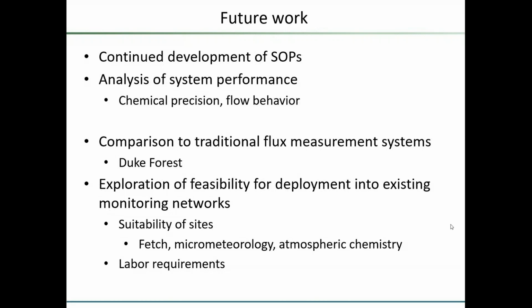Yeah, that's a good point, Brett. I think if you do sample too frequently at these low flow rates, you would run into that problem. The way that we do it is that at the end of every 30-minute period, we calculate the micromet parameters, and then based on what they are at the end of the 30-minute period, we switch the valve. So the valve stays in a position for 30 minutes or longer if the met conditions maintain consistency. So we're sampling over a minimum of 30 minutes to each channel.